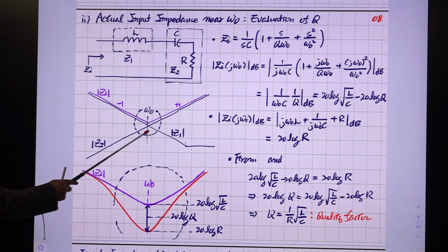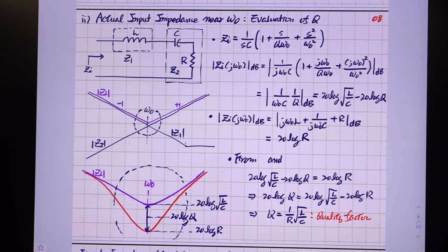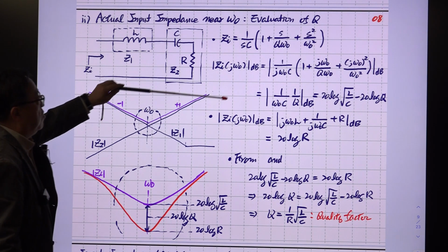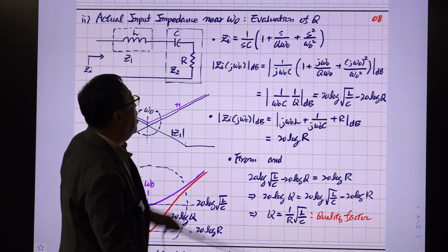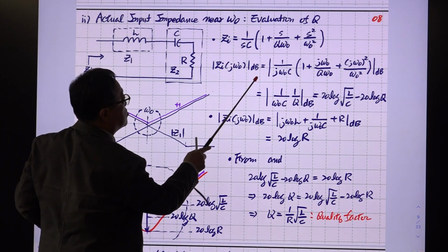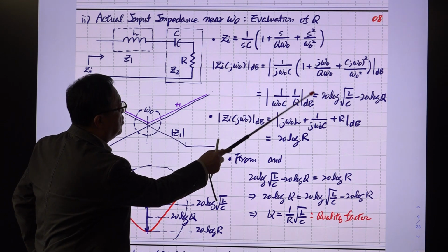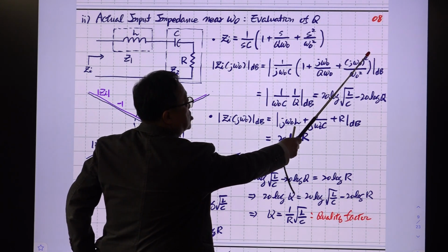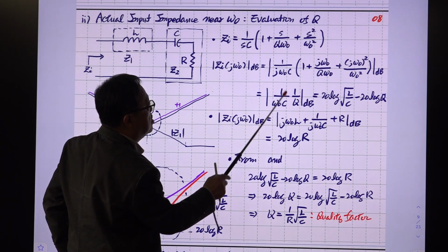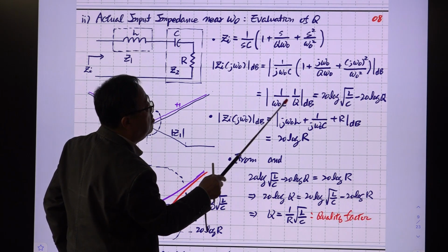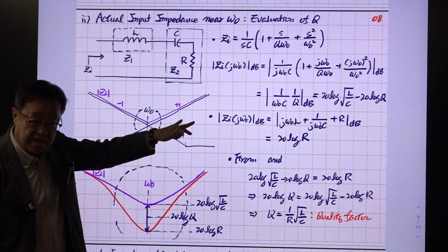So previously we went through this. This is the asymptotic plot of this combination of three circuit components, and the expression of this is this, right? Based on this asymptotic construction, you have this, and the magnitude of this at the resonant frequency. So we use j omega naught here, then this becomes -1, they cancel, so the remaining is this. So only this omega naught C remains here, and 1 over Q is coming in the midterm, right? So this is in dB scale.